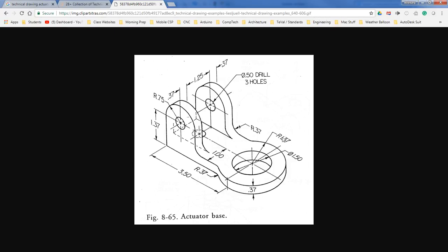So as you can see, this is a radial dimension and this is a diametric dimension. So you would have to double this to compare the size differences between the two, or you'll have to have this. Okay, so 0.75 radius compared to a 1.37 radius if we were to talk about the radial equivalent of this 1.5 inch diameter. Alright, so at least now we have a mental idea of how we're going to model this. Let's do it.